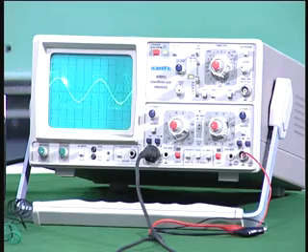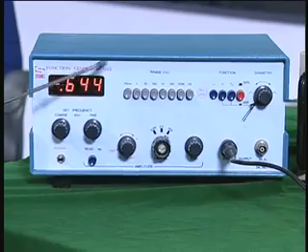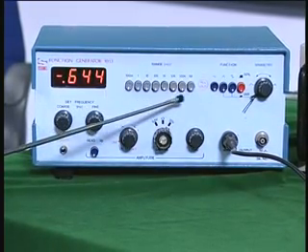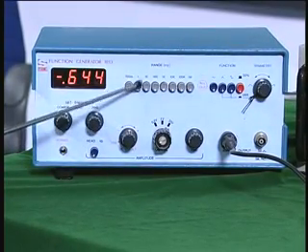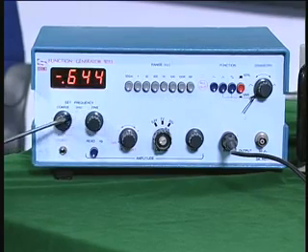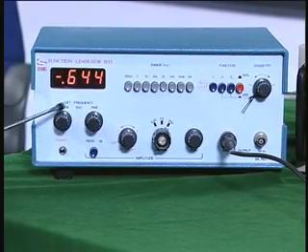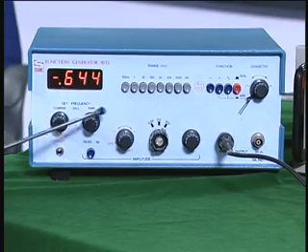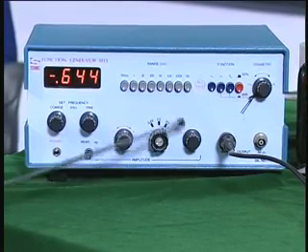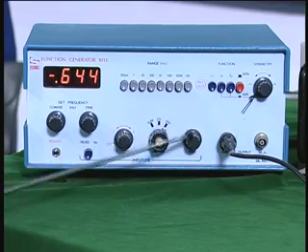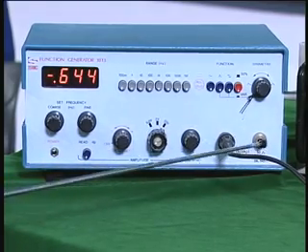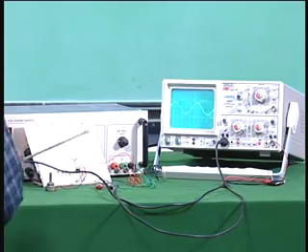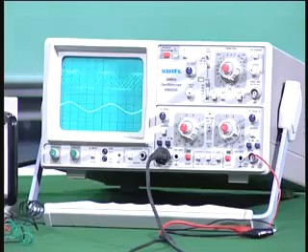To determine the frequency of oscillation, I am also connecting a function generator here. You can see that this is a function generator. You can select different frequency scales here, 1, 10, 100, etc., and you can vary the frequency using these 2 knobs. One is for fast variation, the other one is for slow variation, coarse and fine. You have output voltage controls here, again coarse and fine, to vary the amplitude, and the output of this I connected to another channel of the oscilloscope. In the oscilloscope you see 2 channels.